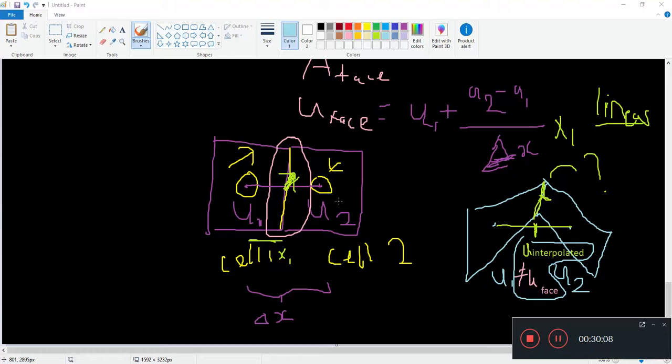There are a few ways we can play around with fvSchemes to solve this problem. But if your mesh is so bad, then this can actually spiral out of control and possibly lead to other problems in the flow, the stability of the flow, or the stability of the solution. So this little error could be a very important reason why we see the temperatures fluctuating like crazy just now, and that is due to a bad mesh.